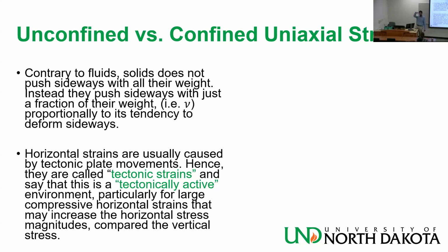So unconfined means nothing on the side. I push from the top to the bottom, let's say, and I let it deform as it wishes on the sides. But if I hold it, I put stress like this, then I'm constraining its deformation on the side. So by Newton's third law, if it's trying to push out, but I'm not letting it, I'm basically pushing it inside.